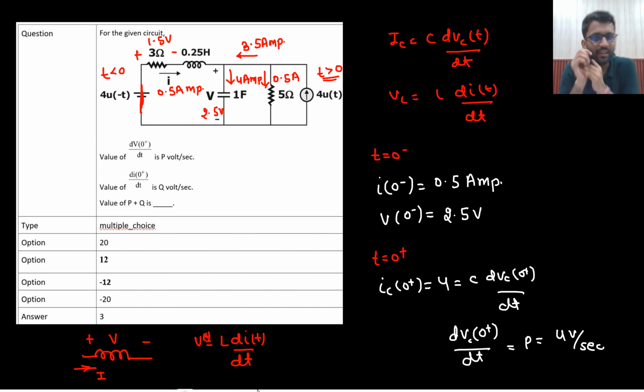So my target is to find the voltage here and here. Here the voltage is minus 1.5 volt, because this is 0, so 0 minus 1.5 is minus 1.5 volt. And what is the potential here? That is 2.5 volt. In which direction do I need to write the potential? From left to right, in this direction. So this is minus 1.5, this is 2.5, so this would be minus 4 volt. So this potential is minus 4 volt.